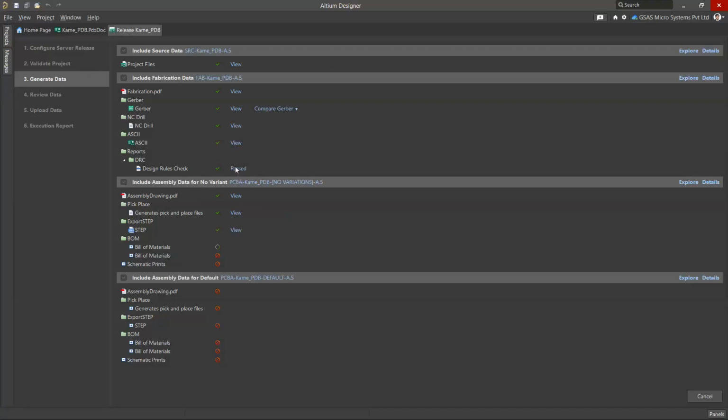If it won't verify, it won't release the data. But when you are manually releasing, the tool won't know whether DRC passed or failed to release the data, as we have given the comment. With this, if DRC fails, it won't move to the next step, which is very good. Then you will get some time to rectify the issue, and then you can run this process again, which is error free.